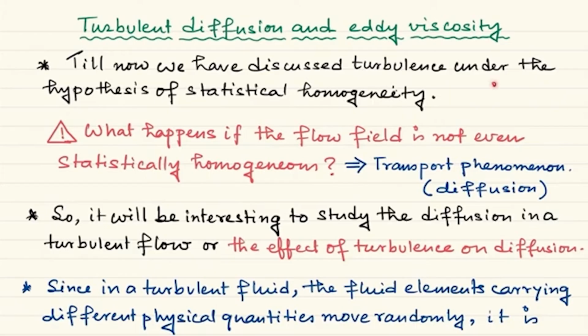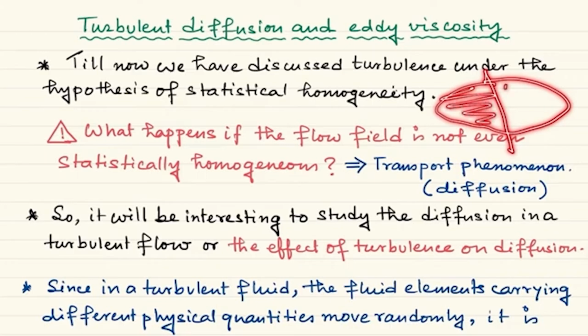For example, if you have a flow field in which this part and this part cannot be compared with each other, then the turbulence over here cannot be put together with the turbulence over here in a global homogeneous framework, right? So then you have to take subdomains like this and this, and within each subdomain you can think of homogeneous turbulence.